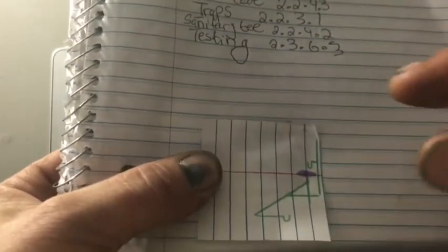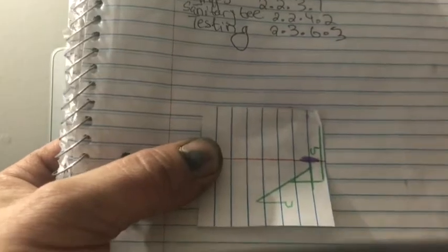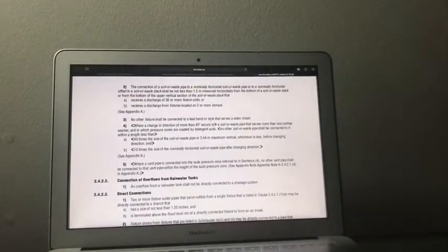So we had to have 3/4 of an inch of space of pipe showing. But obviously that code is saying otherwise. That's why I say I don't know if you had a talk with somebody and we were actually granted permission for that, but clearly they say no other fixture shall be connected to the lead bend or stub that serves a water closet. Okay.